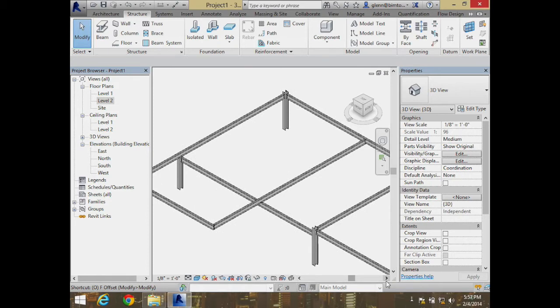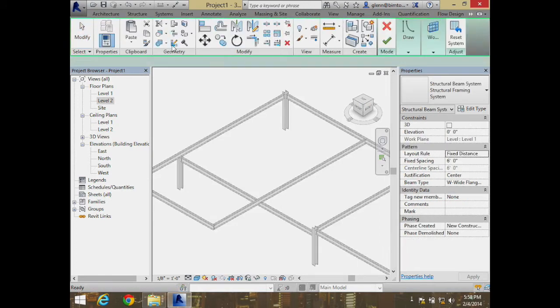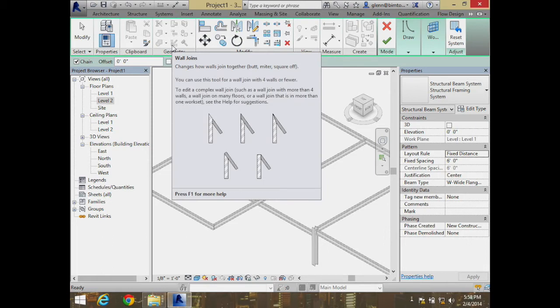Beams are simple elements. Beam systems are combinations of beams that all work together. So for example, if we had a rule that said the longest span we could have on the concrete decking is 5 feet, we would put a series of elements going in the other direction every 5 feet, or maximum every 5 feet, so that the steel decking can be supported. And how we do that is actually this thing called a beam system. Now, beam systems work amazingly like beams, except that you have to choose some element to use as the standing element.